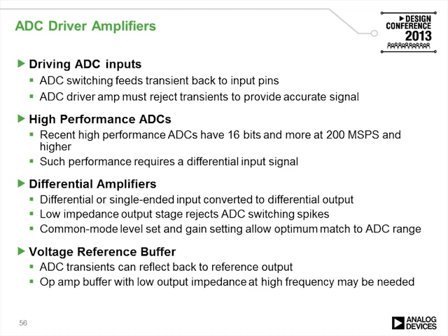Differential amplifiers can take a single-ended input and convert it into a differential output that is required at the input of an ADC. The other input for the ADC is also the reference input. And for this input, another ADC driver may be required, such as an op-amp buffer.